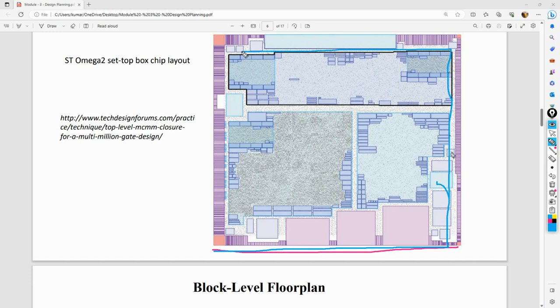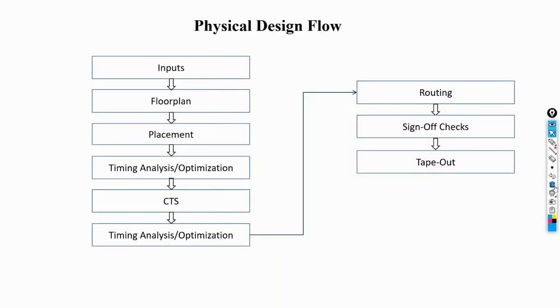Okay, you still make more money or save more money than what you are actually doing. So that is the reason. Say now, do I really need to place all the IPs here? Is there any other better place which would make me bring down the size and so on? So the whole analysis happens at the time of your floor plan. Floor plan is the first step, where it is very critical in terms of your area estimation and then area optimization and so on.